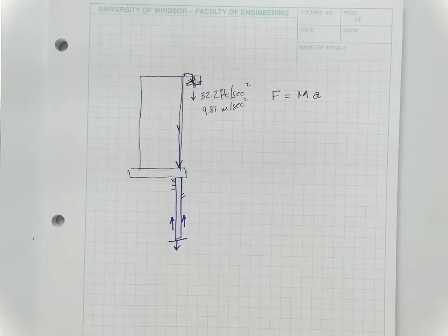And the interesting thing is, if we were to blow out all these walls in here, which are only demising walls to keep the hallway separate from the classroom, and we were to blow out all the brick out there, take the roof off, the frame stands all by itself. The frame is the bones, it's the skeleton of the structure that carries those loads. And as designers, we look at where all of those loads are when the building is up.